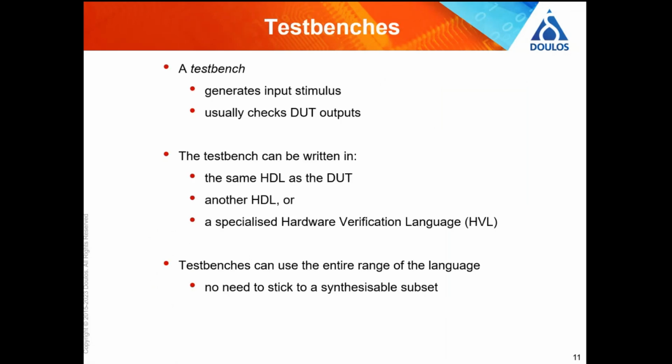So what you're going to need if you're doing simulation is a test bench or a test environment. This is the code that has certainly one job, as I've already said, which is supplying the inputs to your design under test, but really should have two jobs, the other being checking the outputs from your design under test. Design under test, DUT. That's what that means.